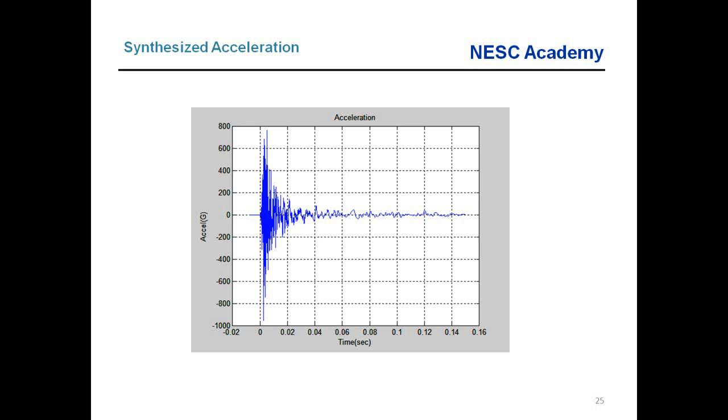So after all is said and done and maybe 20 minutes have gone by, we come up with an acceleration time history as shown here. As we look at this, with a little bit of artistic license, I guess, this could represent a far field or maybe even a midfield pyrotechnic shock event. It's plausible. Now there's no exact criteria saying, oh yes, that does represent a pyro shock or not, but in a broad ballpark sense, yes, that does look like a pyrotechnic shock for far field or midfield.